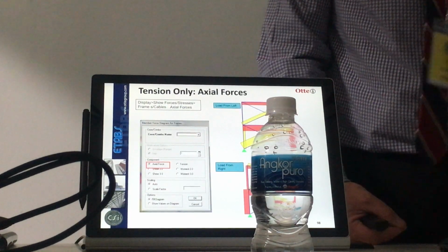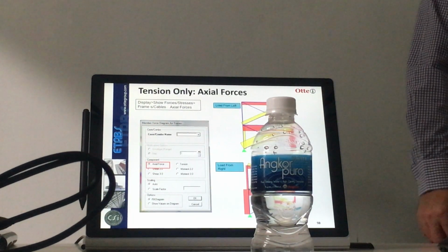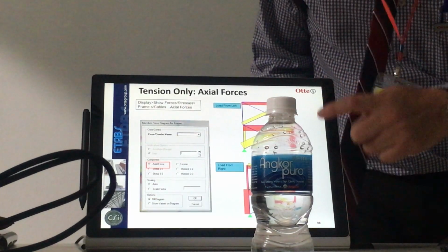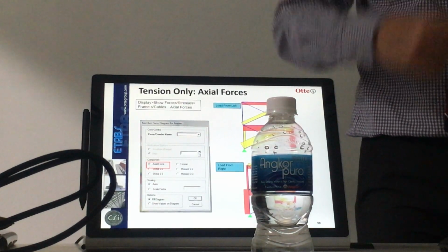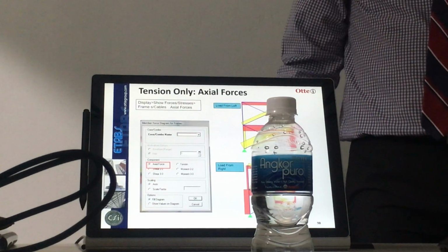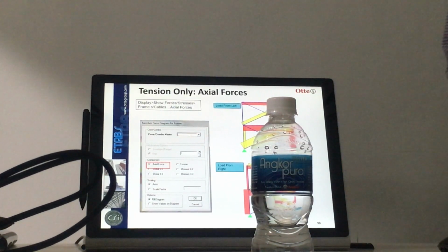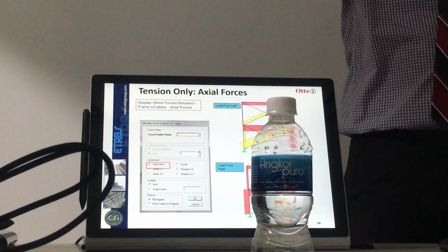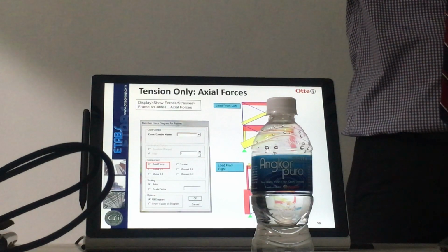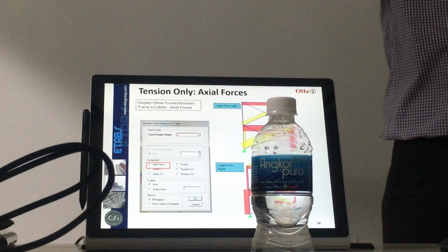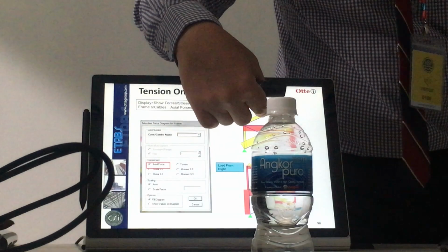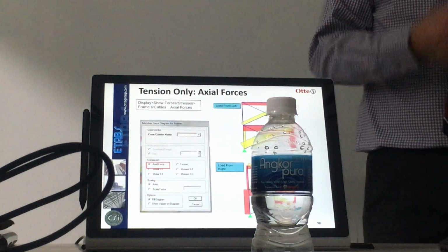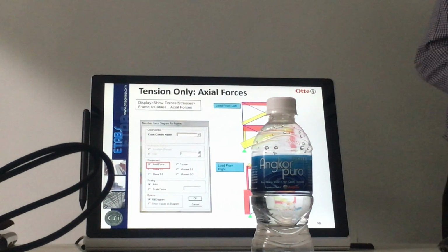So if you use principle of superposition, when the load is all together, you will add this plus this, then both of them have tension. That's what you get by principle of superposition. But in real life, if you put two together, the brace is not working anymore because it cannot take compression. So it's actually zero load. But if you use principle of superposition, you have tension and tension add together, so both of them in tension. That we can explain why we cannot use superposition when you do nonlinear.